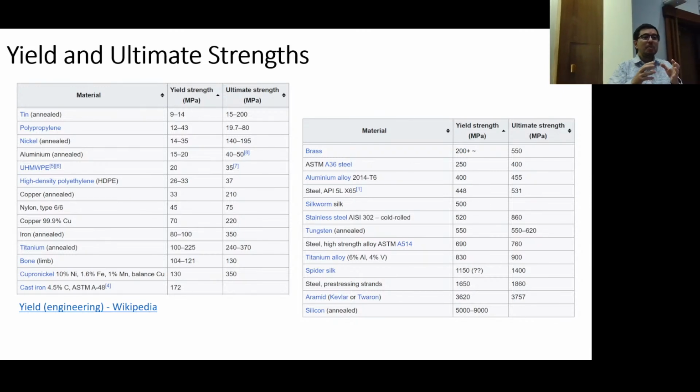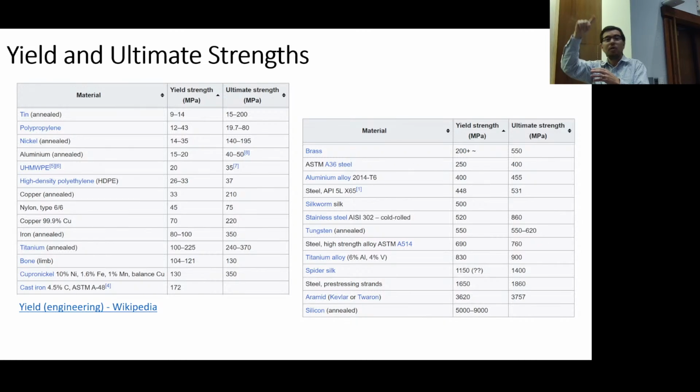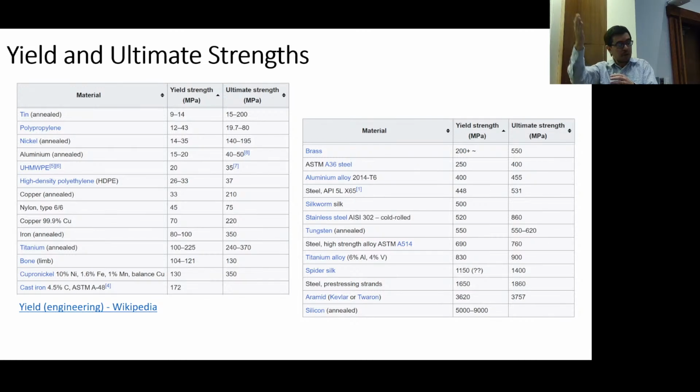So you can think about that, right? And we've talked about that, right? We've talked about strain hardening in this class, and how if you go beyond the elastic limit, or beyond the yield strength of the material, and you go up that, it does go up a little bit in the stress strain curve. As you unload, you can go back down to zero. There's going to be some residual strain, but now the yield strength has increased to whatever level you got up to.